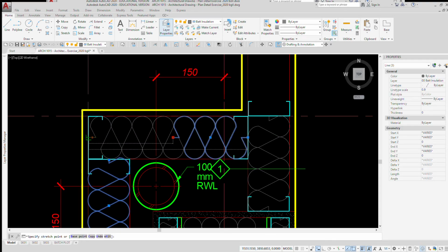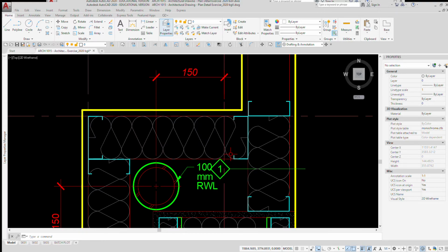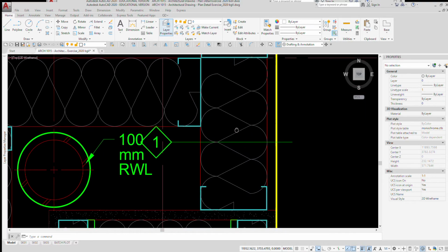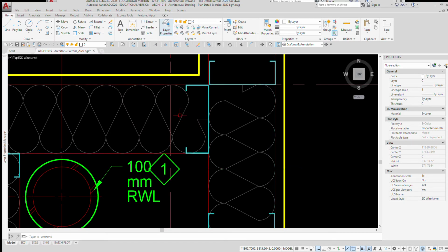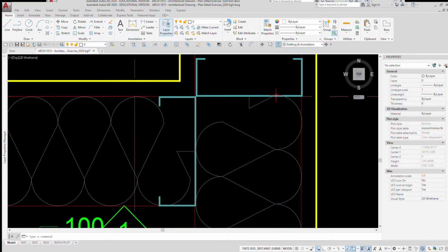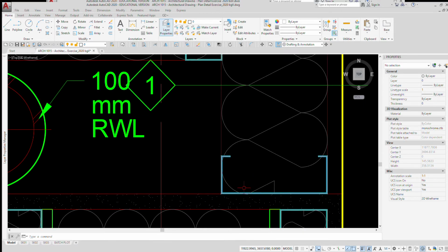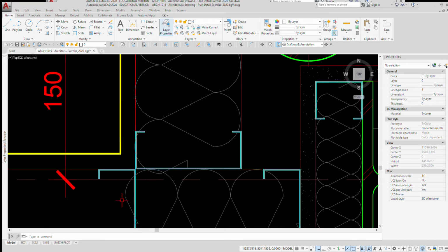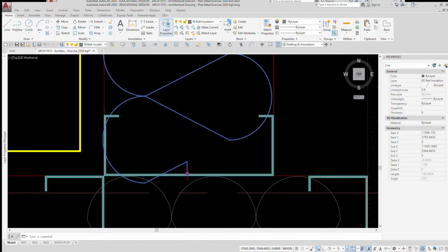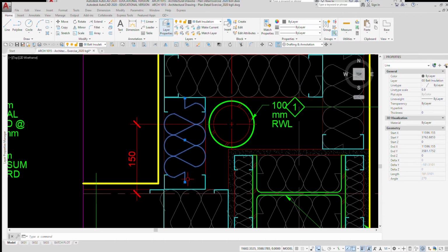And there. So what you're seeing is that that line type's a nice thing, but you're going to have to learn when you're drawing in AutoCAD that sometimes when you use things like this line type that's all set up for you, sometimes it works out great, has a nice look to it, then it starts getting a little on the suspect side of things, and then it really starts getting way over the top. So there's going to be times when you're going to take artistic license. That line type works in a module, so when you go to shorten it, it'll take out a module at a time, right?